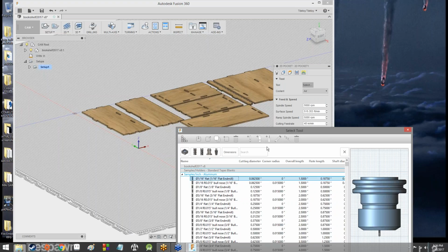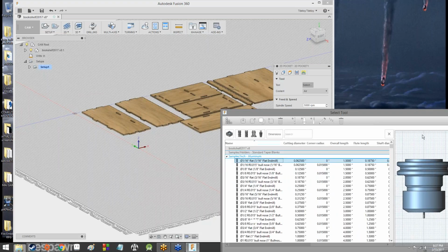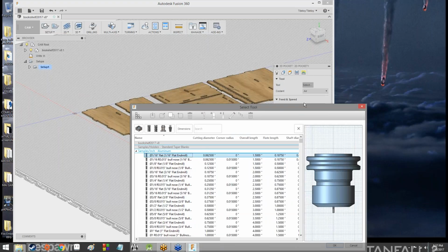If it can't cut out those areas, well, our tabs aren't going to fit very well at all. So we want to make sure that we're using a tool that is smaller than those cuts, because it can actually cut that stuff out as opposed to just mashing itself in there and creating, I don't know, a 3/4 inch wide hole. The tabs aren't going to fit in there. That just simply will not work.